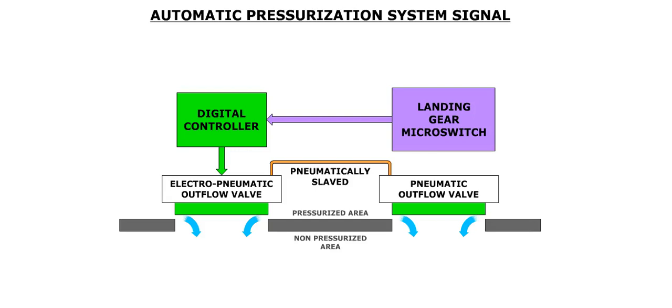The automatic pressurization system gets a signal from a landing gear micro switch, which determines how much the torque motor moves to apply vacuum pressure to the outflow valves after takeoff. The system then maintains the cabin altitude of the takeoff airport up to 3,500 feet, which we will look at more closely in a minute.